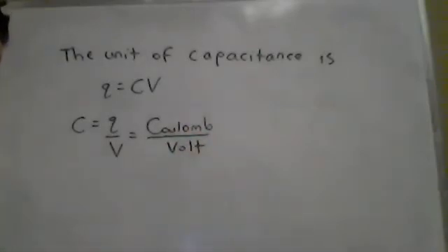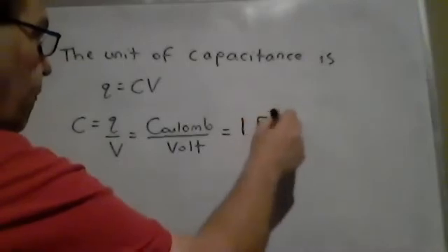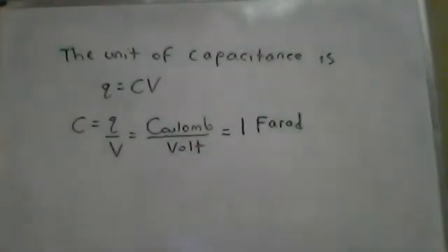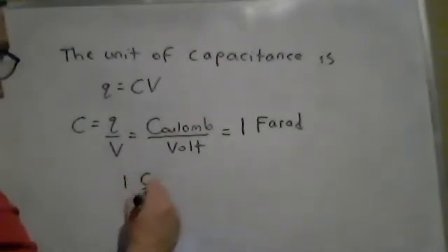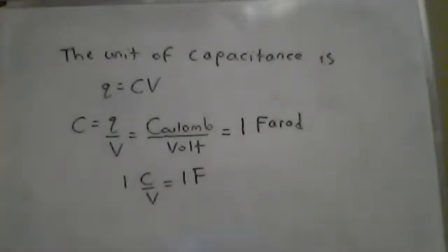An arrangement like that, I call the farad, typically using a capital F. So 1 Coulomb per volt equals 1 farad, and we named that after Michael Faraday, of course. That's the point: we're basically storing charge on the plates of the capacitor.